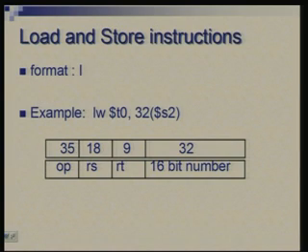Okay. Now, we have seen design for these 5 instructions. We need to now go further. We need to augment this to include more instructions, and we will see that by making small incremental changes, we can accommodate more and more instructions. So, let us address load and store instructions next, and the common thing there is that memory has to be accessed, okay, and the mechanism for calculation of memory address is the same.